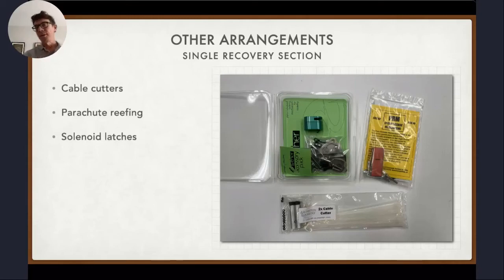I don't think it matters if the charge is in front of or behind the parachute, because what you're really doing is just releasing gases to open up and separate the two sections. And the shock cord is going to pull the parachute out of the airframe as the pieces move apart through the ejection charge action and through the air. So it's really just a matter of opening the rocket. It's not really pushing the parachute out.